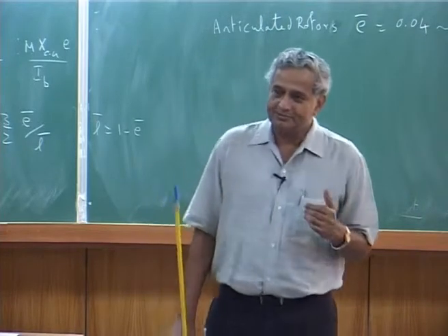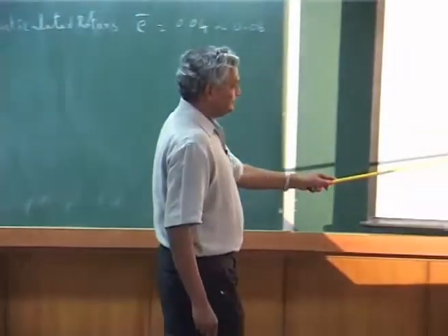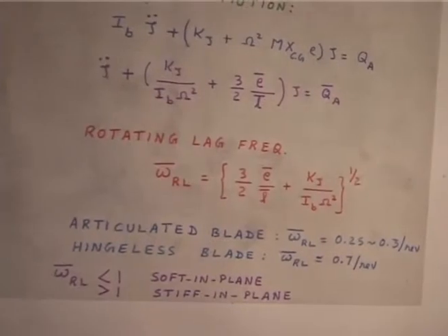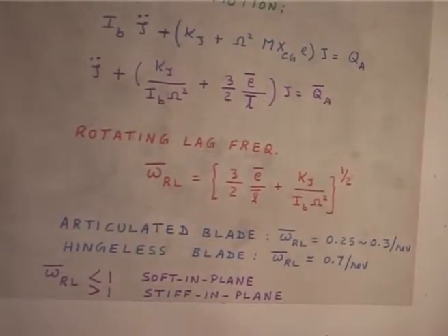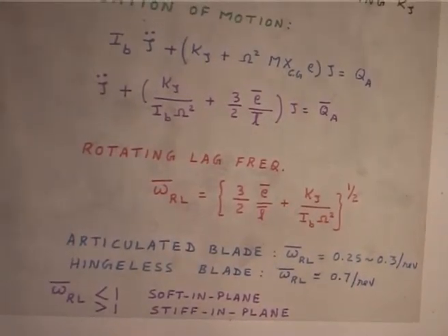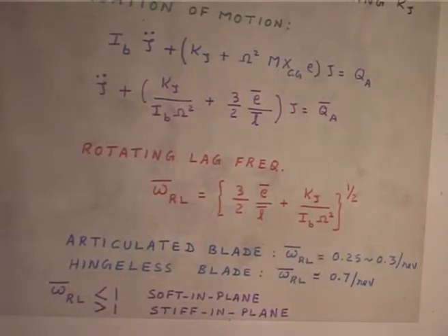Tail rotor systems, by design you try to have it stiff in plane and then keep the frequency away, but make sure that the frequency is far away, and then you do not have a damper, absolutely no problem, but loads will be high, but you live with it, because tail rotor loads are not very high, so it is okay. So you see, in the design and the selection of rotors, the frequency placement plays a major role, and depending on where you place it, you have to add an additional system, because the system can go unstable. So you say, okay, I have to put one more damper.